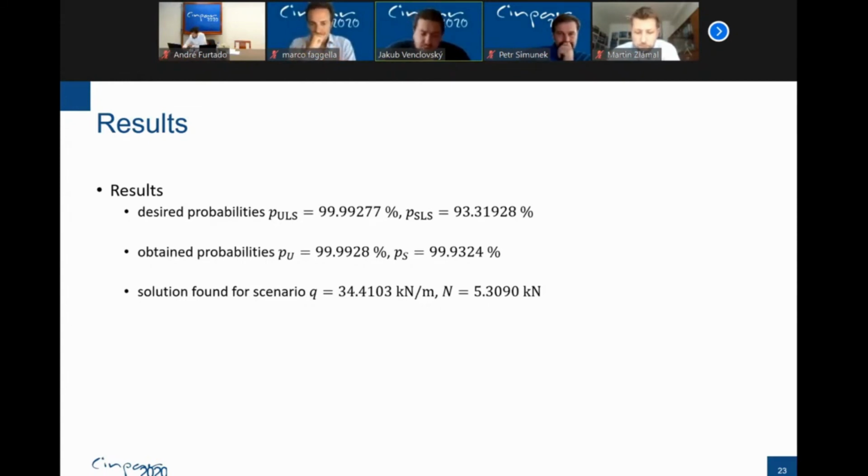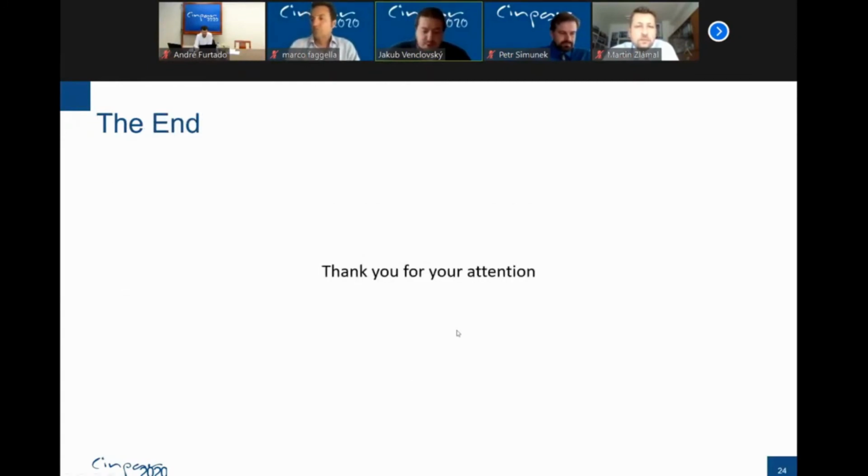I didn't include the solution itself because, in this concrete example, I allowed the design variables to be different in all finite elements. As I mentioned, there are finite elements, and I allowed that in each finite element the design variables can have different values. So since there are 10 finite elements and 8 design variables, it is overall 80 variables. So I guess it was too much.